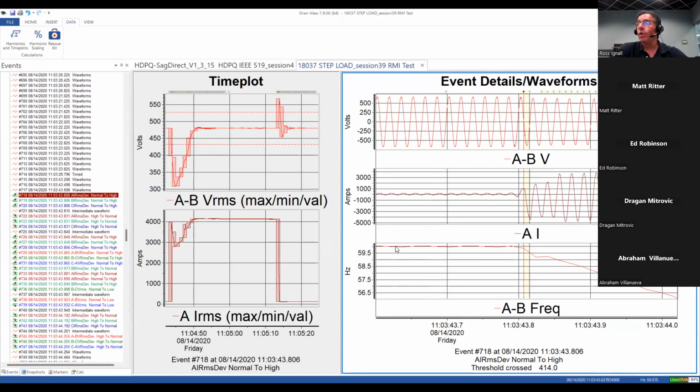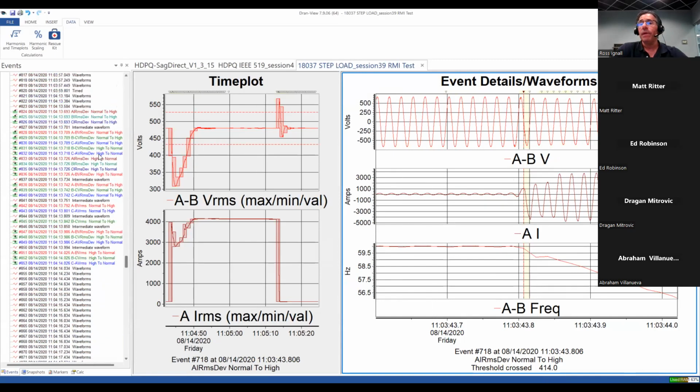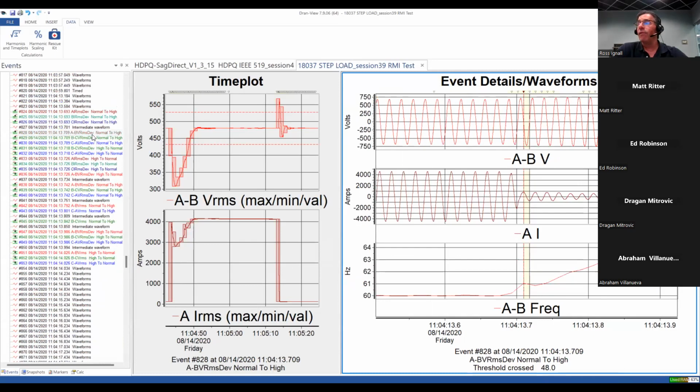So you can see it went to a little below 60 hertz. You see how it drifts down when this particular voltage goes up. Anyone that I select, I can go down and look at them. You could see what the cycle by cycle frequency is. So you can see the load turns off here, and you can see how my frequency drifts up at the output of that generator or that UPS, whatever they were looking at. Okay, thank you again for correcting me before.